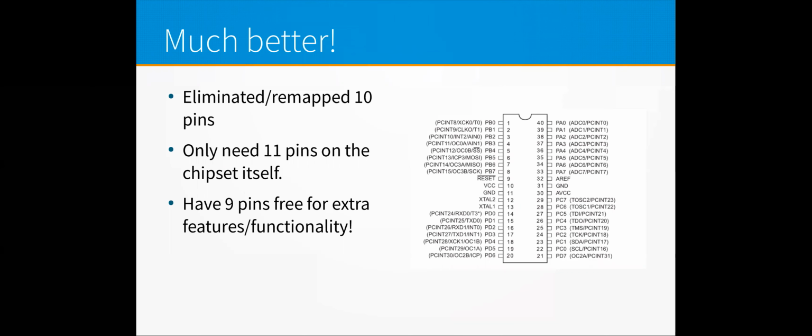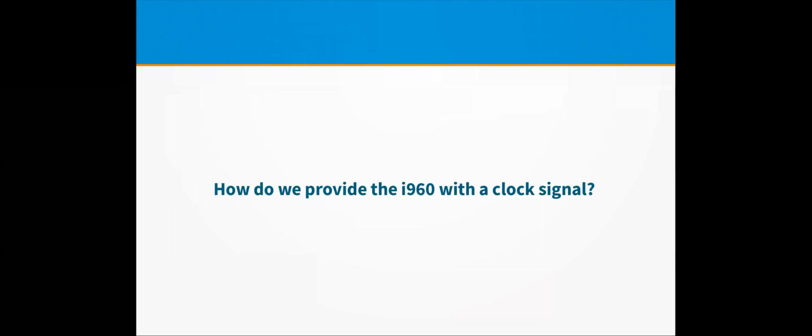But the next question is that the i960 is a synchronous processor, and you need to provide it with a clock signal. Obviously, I could get a 20 megahertz crystal and just hook it up to it and call it a day.